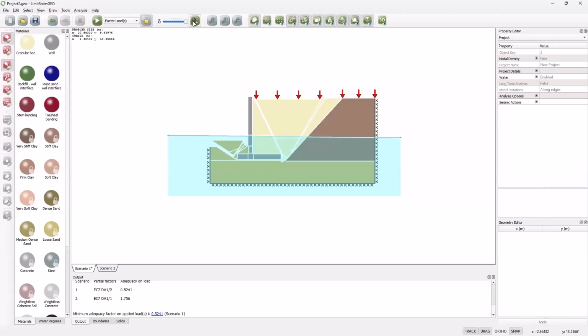Can we model geogrids as basal reinforcement? So it is possible to model geogrids, and the software models those in the same way that most conventional analyses do. So yes, you should be able to use it as basal reinforcement, but it depends particularly on the analysis method that you're trying to adopt, or the mechanical properties of the reinforcement. We can perhaps answer that question in more detail separately.